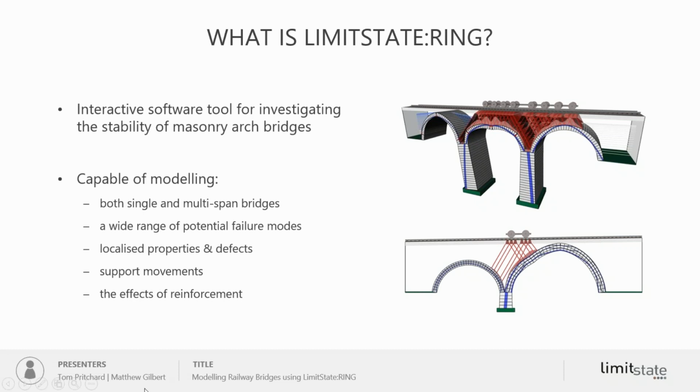And also a slightly esoteric feature, I guess, is we can actually put in reinforcement into the analysis as well. Personally, I have mixed feelings about putting in reinforcement. I think if you're going to upgrade your bridge, there are normally more effective ways of going about that. But you may inherit a bridge which has reinforcement, and you can take account of that in the analysis as well.